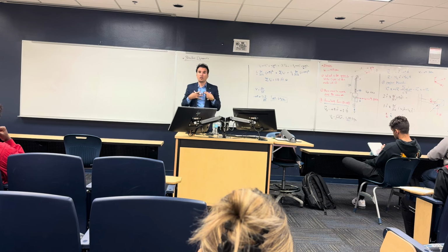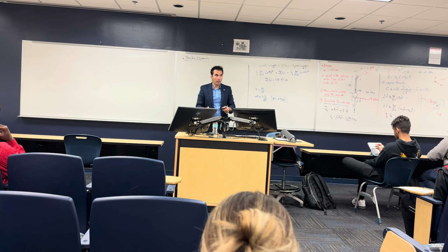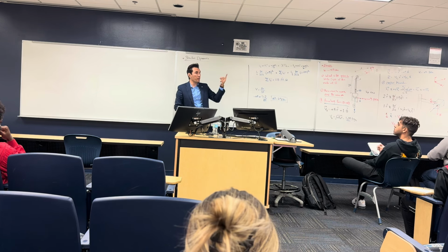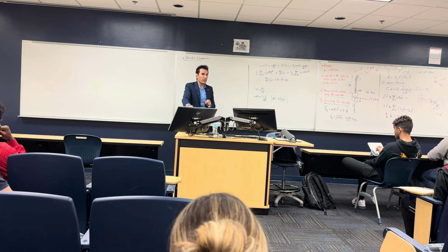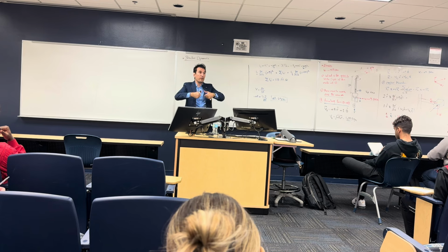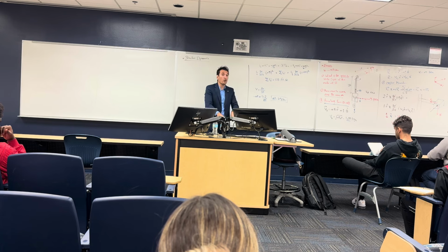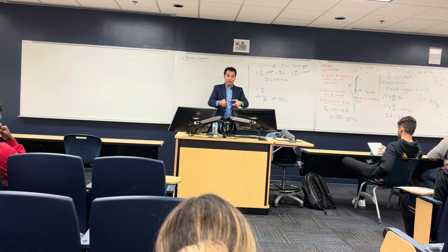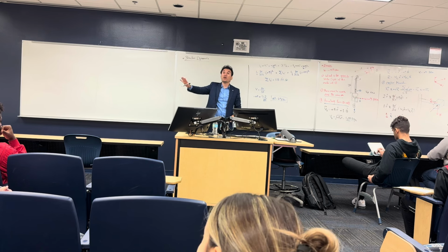Let's say I'm a structural engineer and I'm going to design this floor. I care about two things, which we call serviceability and resistance. We need to make sure that when we all sit on this floor, it doesn't fail, meaning the bending moment does not exceed the resistance of the concrete or the steel, because then the whole floor can fail. We call this failure.